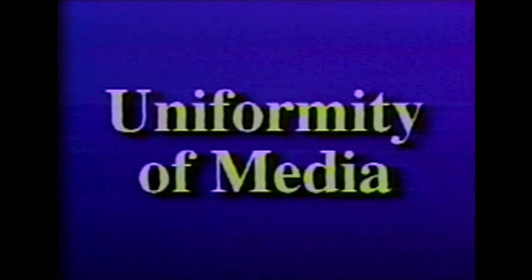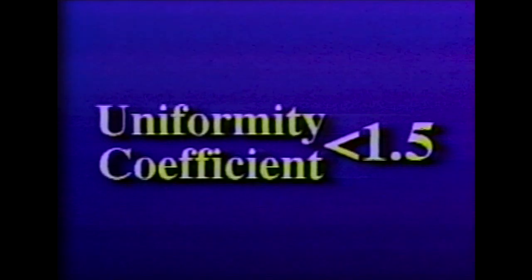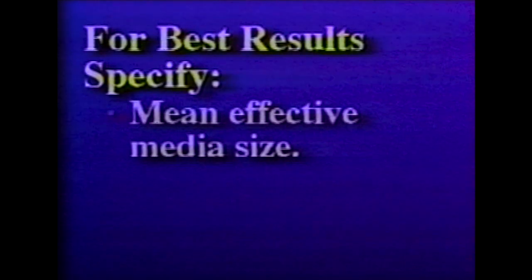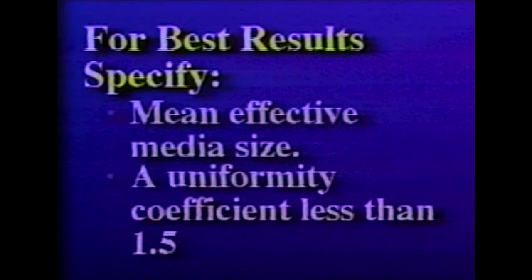A second consideration is the uniformity of the media. A good media uniformity coefficient is less than 1.5. For best results, one should specify the mean effective media size and a uniformity coefficient less than 1.5.